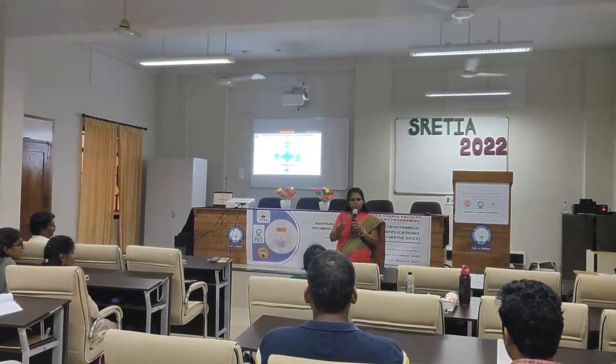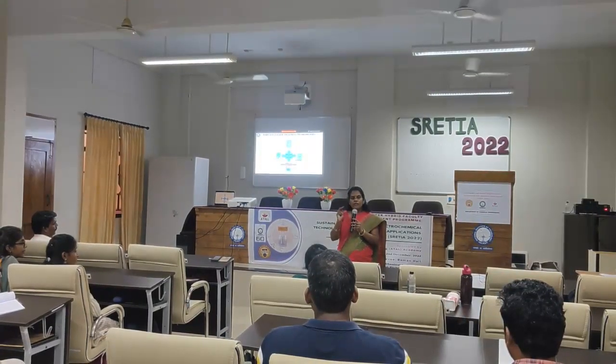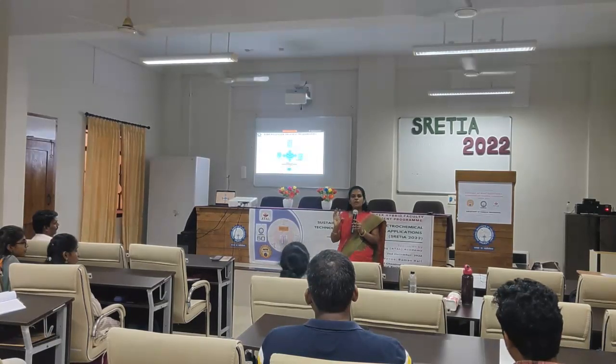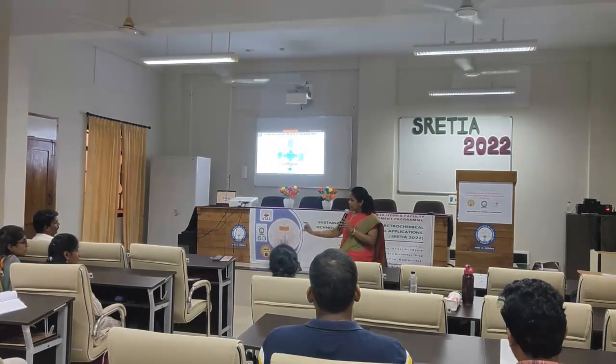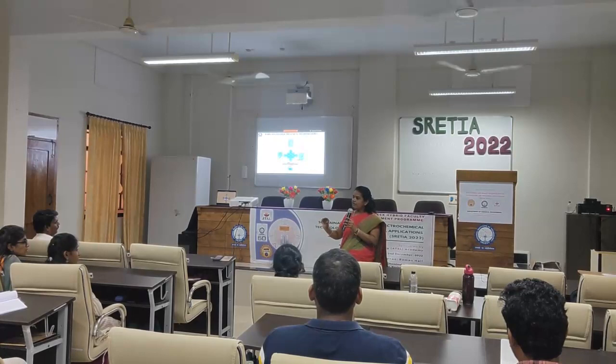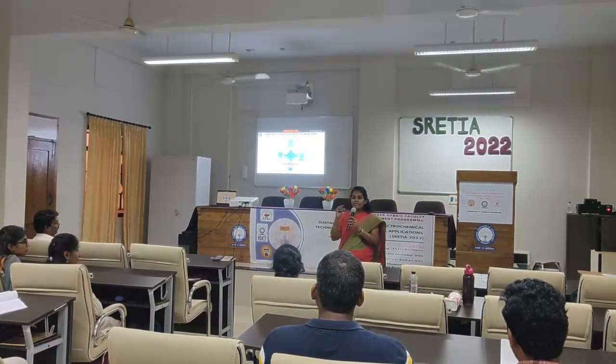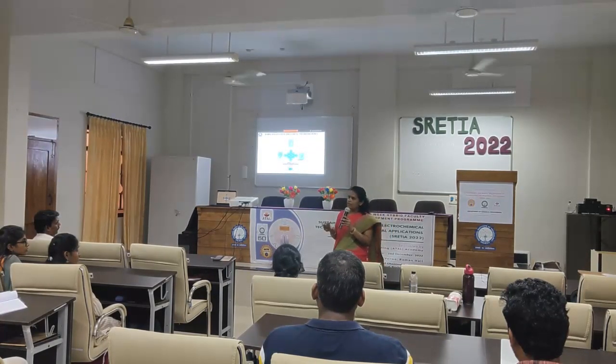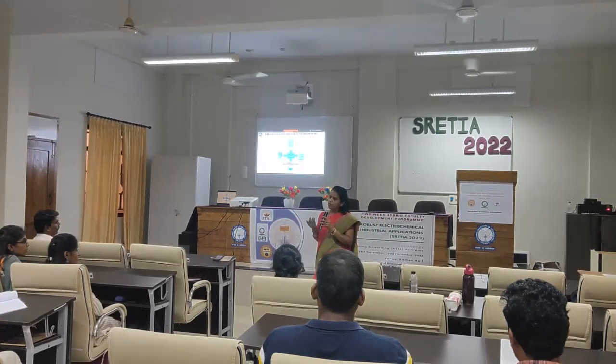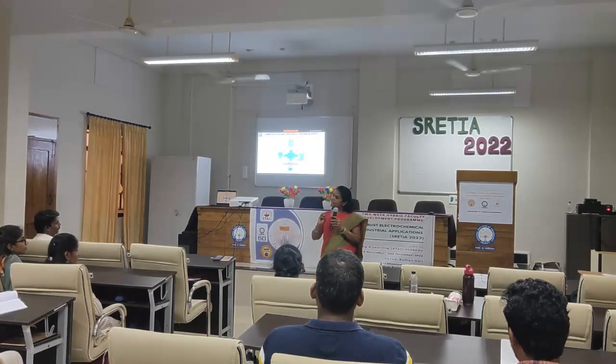Okay. This emulsion we are preparing from oil and water will look like a homogeneous phase only for a short time, for half an hour or 1 hour when you keep it there and measure it. After 1 hour, you can clearly see two distinct phases, one will be oil, one will be water. Where can you see the oil phase, top or down? Top. Why? Its density is lighter than water. So it will split.